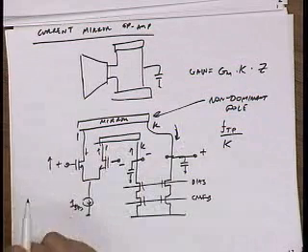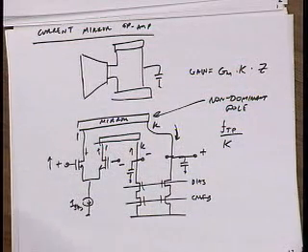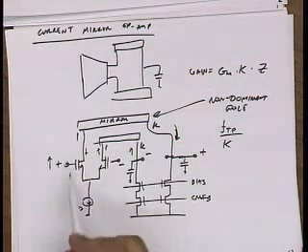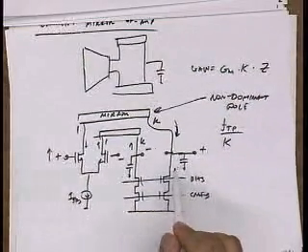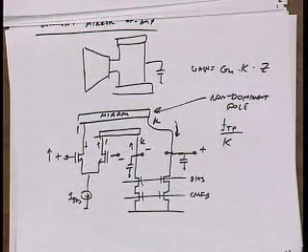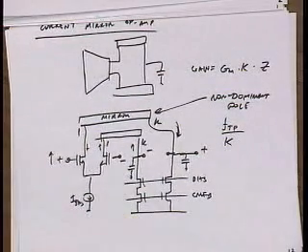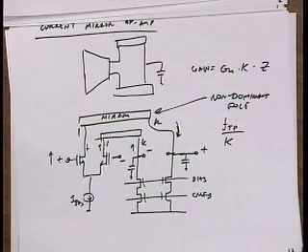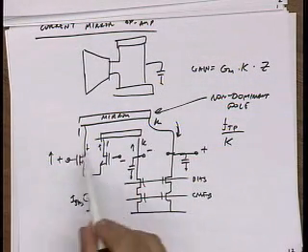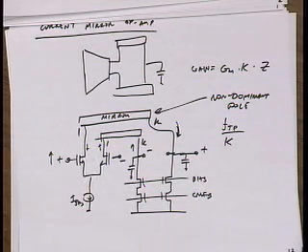So, you know, this circuit would work perfectly well if I had used a P-channel input, right? PMOS version, and mirrored upwards, right? What are some of the benefits, advantages, disadvantages using NMOS versus PMOS for the input stage? It's very similar to a folded cascode, right? So in folded cascode, I can have an NMOS input or a PMOS input. Which would you use?